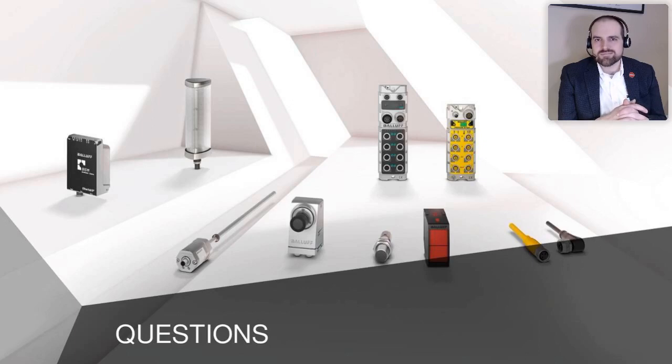We have a question from Marvin asking, how can I integrate the sensor into my machine? Yeah, there's a lot of options. The one that most people I've worked with are using is their industrial controller. So their existing Allen Bradley Rockwell controller, their Siemens controller, and it has to have IO-Link. Siemens makes cards that go in the rack or for their remote I/O system. So does Allen Bradley, which makes cards for the point I/O system.